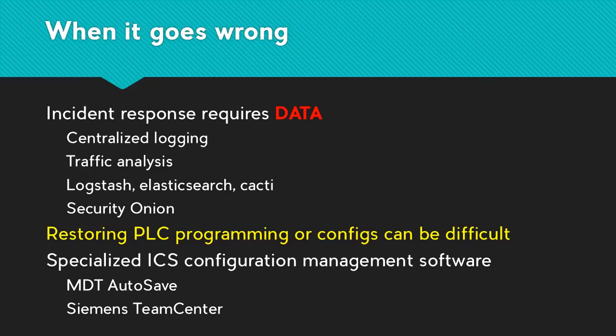Restoring PLC programming, this is a little bit off topic. Basically, you can't just connect to a PLC like you can a router, switch, and firewall and pull a config off in a human-readable format and store it in a database. These are binaries, and depending upon the vendor, you may not even be able to back up the binary. You may only be able to back up the config on the engineering workstation that wrote it.